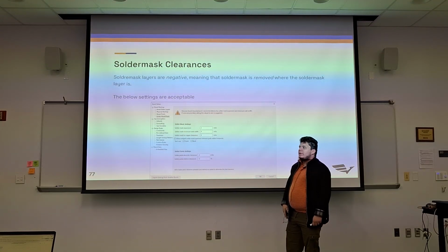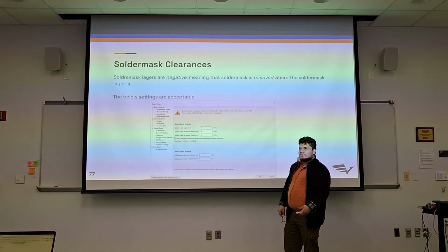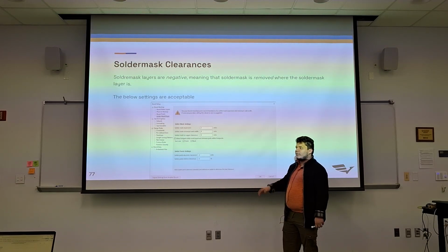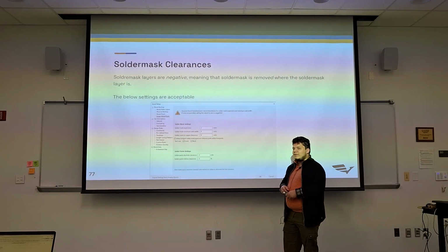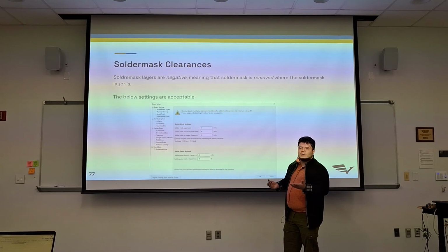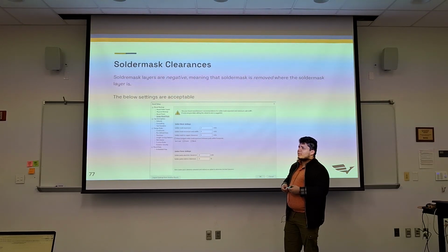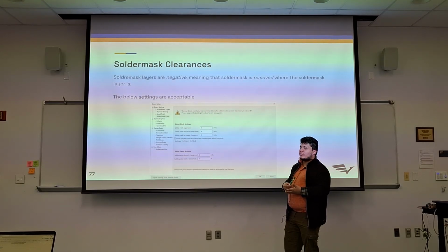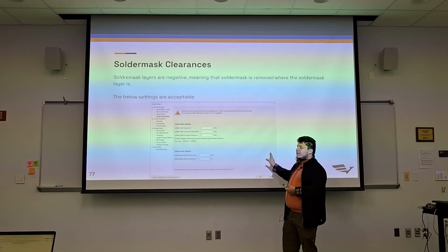on the board. Historically, you always go with green on white since green is in the middle of the color spectrum, so it's easy to differentiate pads, components, and solder mask. That's why we've always seen green on white. Typically, test equipment is blue, and I forget what red is for; I've usually seen that on motor drivers and stuff. But anyway, the solder mask layer is a negative.